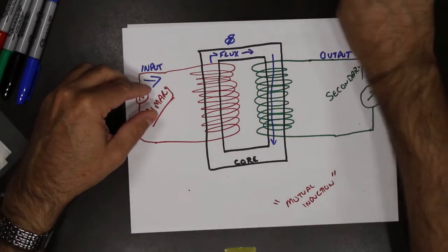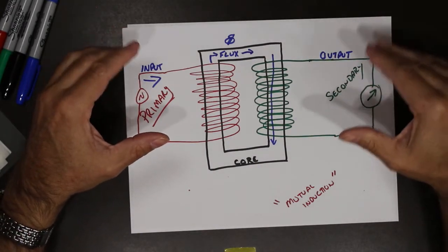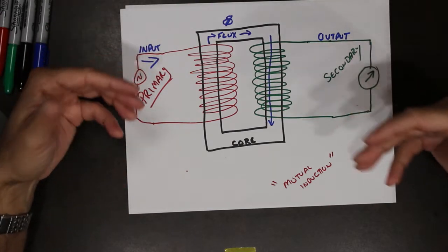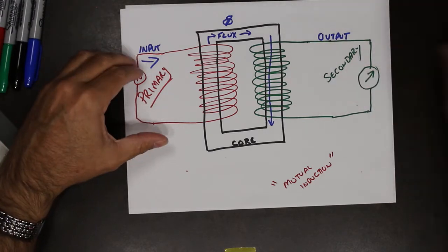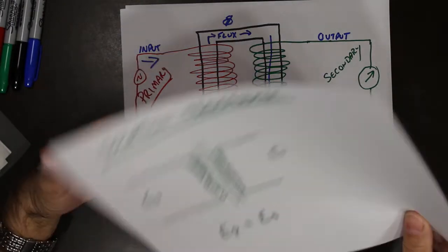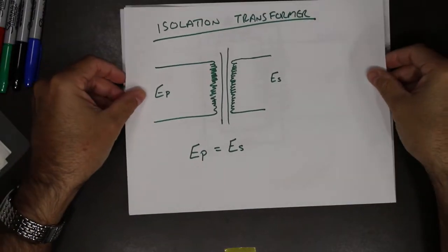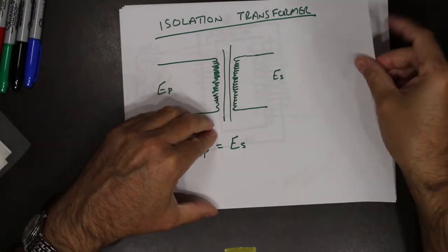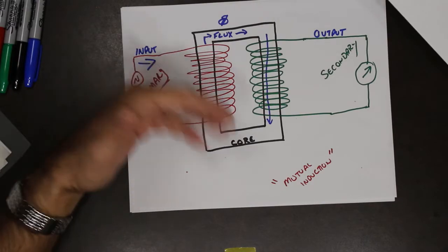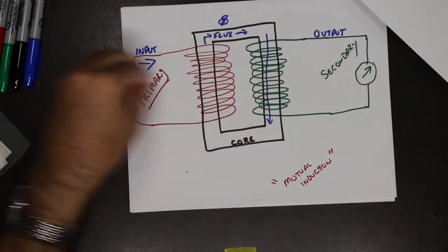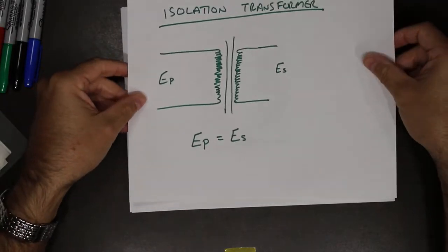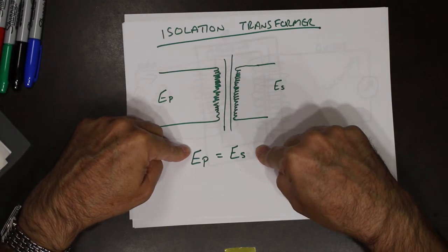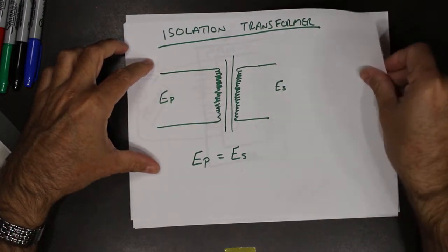Being electrically isolated is one of the big advantages, or one of the good things that happen in a transformer. So if you wanted to electrically isolate something without changing the voltage, you would use an isolation transformer. Regular transformers do the isolation part as part of being a transformer. So they isolate and change the values of the voltages. Whereas with an isolation transformer, you gain the isolation without changing the values of the voltage. So that is another type of transformer that is available to us.